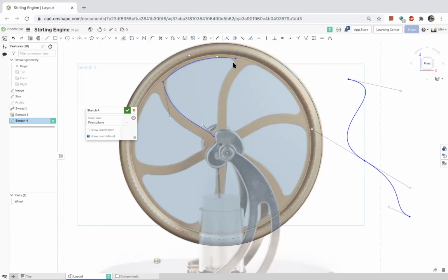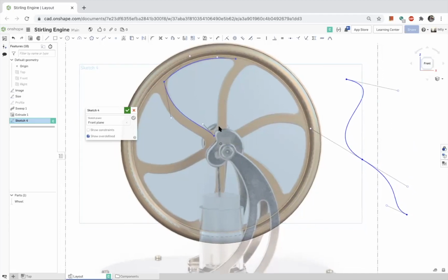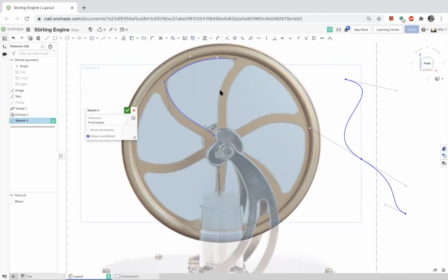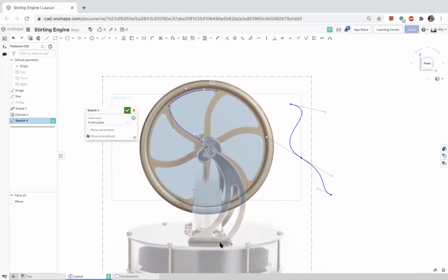So this is my point here. I see this and I see one inflection point. Therefore, I know that I can represent this as a spline. I don't see anything in this design that has a very complex curve, right? This curve shape goes down here, one inflection point. So let's say I want to represent this whole piece here with one spline. You see the part that I'm drawing on my screen? That would require multiple segments of a spline.